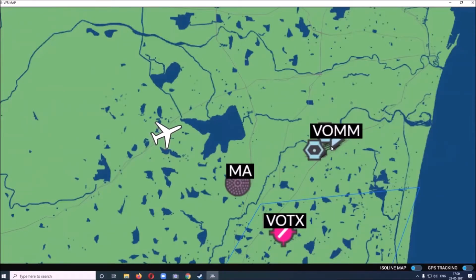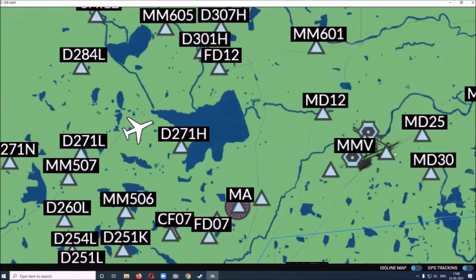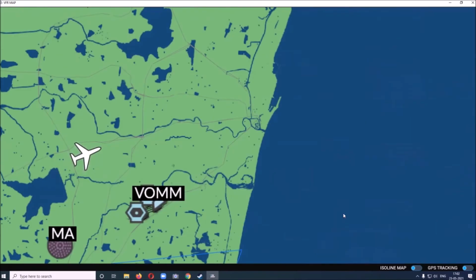This is Chennai. We came out. This is runway 25. We came out this way. Now we are turning back on a heading 070. This is the Bay of Bengal. So we'll come over here and somewhere around 15 nautical miles, we'll take a turn and intersect the runway center line to capture the instrument landing system.